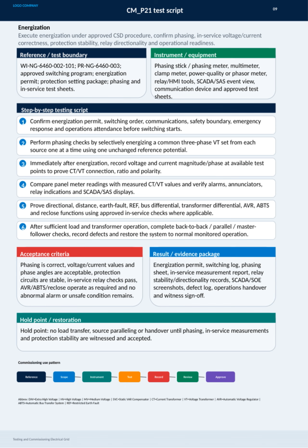Finally, a crucial hold point is established. No load transfer, source paralleling, or handover occurs until all phasing, measurement, and protection stability checks are witnessed and accepted, ensuring safe and reliable grid energization.